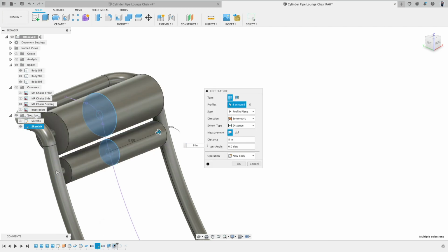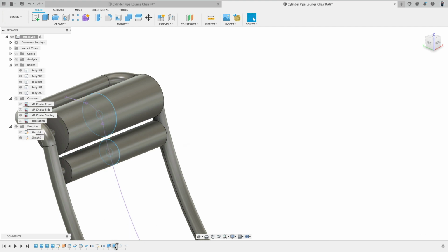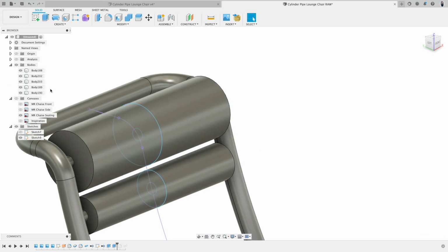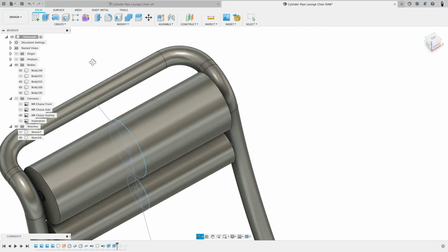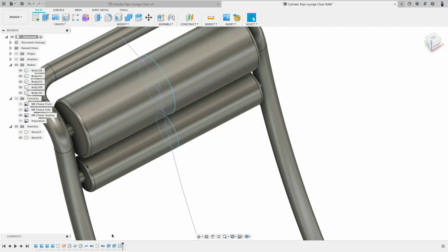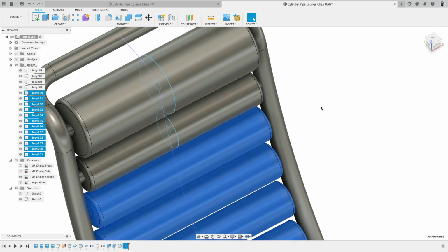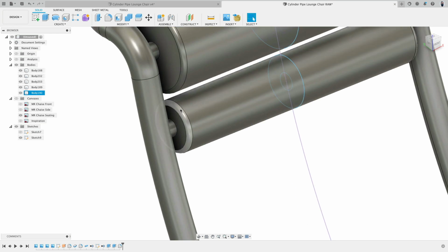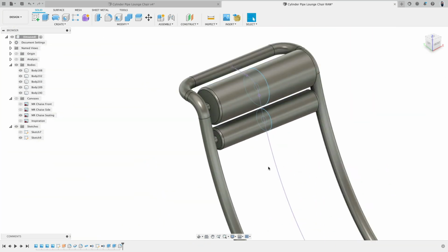And then when I go back to here and right click, edit this extrude, I need to make sure that I deselect the inner parts because I don't want to have this to be solid. There you see how we have the holes there. The fillets then remain, very good, all nice. And then here, this command I will delete because I will now make a flow with both here.